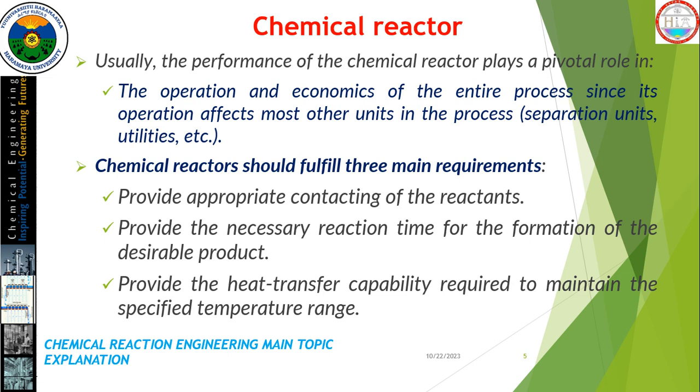Because the rate is directly related with time. So the rate of reaction is directly related with the product as well as the reactant. So it is necessary to provide reaction time for the formation of the desired product. The third one is to provide the heat transfer capability required to maintain the specified temperature range. So within the specified temperature range, it should enhance the heat transfer rates.